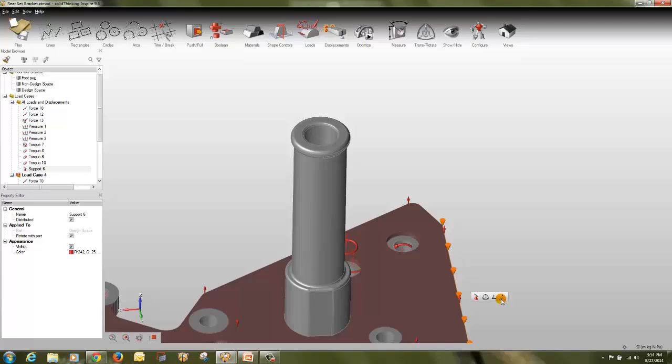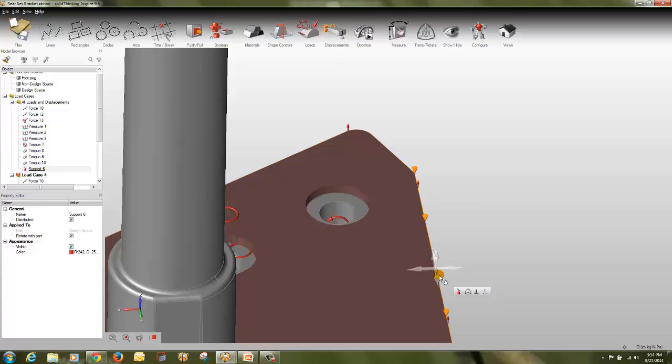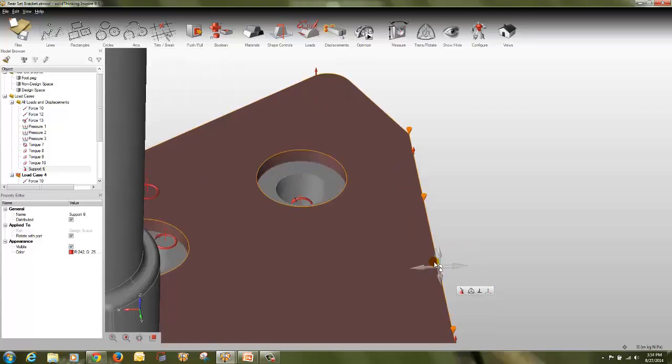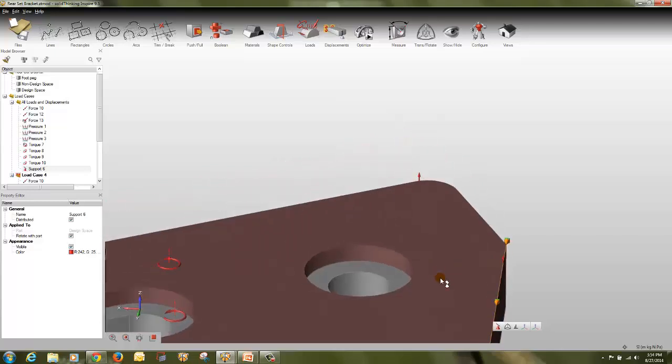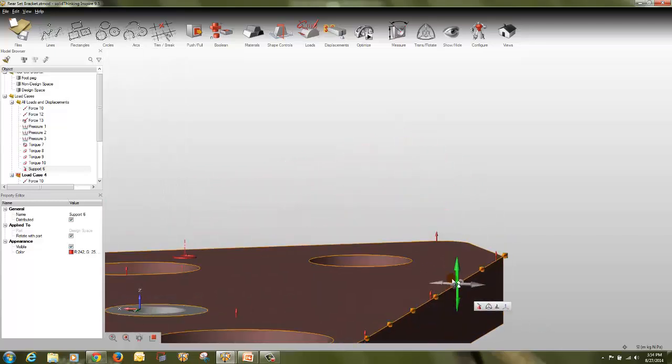Perpendicular to the edge, single and multiple. Then if it's all transparent, that means it's constrained to all the degrees of freedom. If you tick any one axis, that means it is free to rotate or it's free to translate in this particular axis. So translation is free.